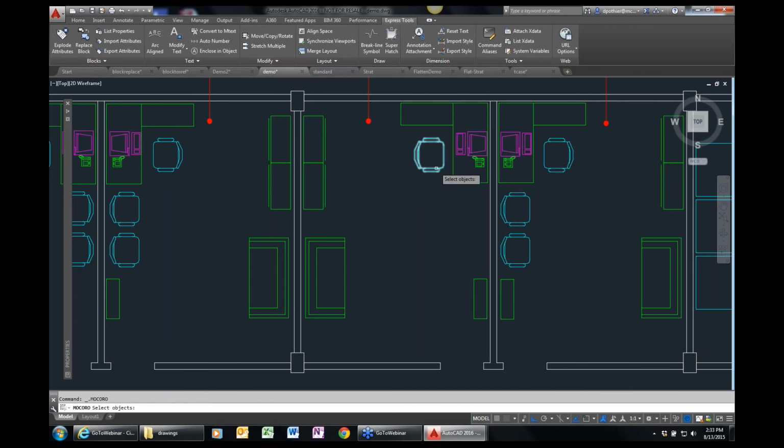We'll go ahead and select maybe this chair, and turn off my object snaps. Okay, and I'm just going to give it a base point, and you see that we get all these different options here. So I want to take this chair, copy it over here and rotate it down, and then create another copy, etc. So we can do this all with one command instead of going back and forth from one command to another.